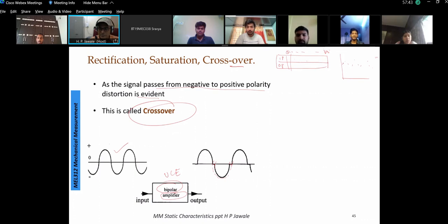And then we can find out the mean. Using the statistical method, we can find the best estimate. Then we can find out what is the maximum deviation for, say, for example, the 8th reading. Let us say this is the 8th reading. We can find what is the deviation of this, or what is the error at the 8th reading. Similarly, we can find at the 9th reading. Then we can have different interpretations. We can find out range, we can find out tolerance band, the span, the random error, the precision error, and so on.